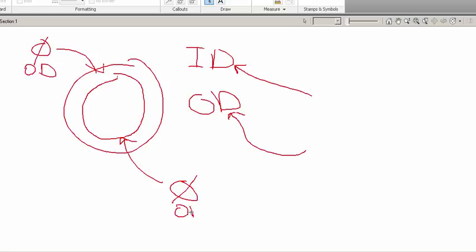And just so you know, the standards are different. Say you go order a 6-inch pipe. If you're dealing with one type of application, you might be dealing with interior diameter, where the interior is crucial. Or you might be dealing with the outside diameter, which might be crucial for a different application. The key thing I'm trying to drive home here is you want to watch out for it.